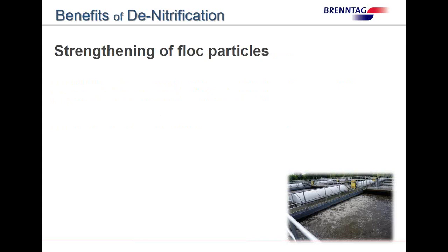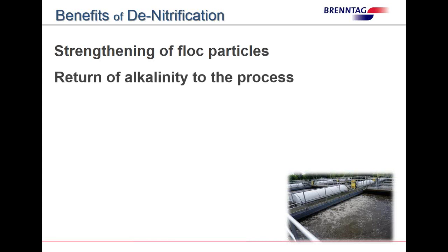Now, here's some of the benefits of denitrification. I love it when people ask me about it, but you get a strengthening of the floc particle, and a strong floc particle tends to want to settle. So we want good, strong floc particles so they settle and don't carry over and make TSS, or total suspended solids, go out the effluent. You get half of the alkalinity back when you denitrify.